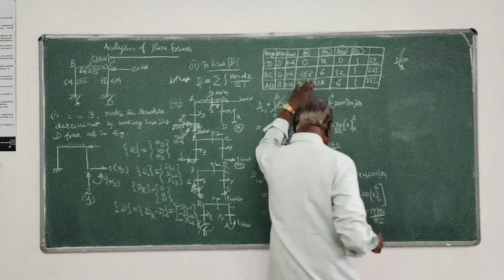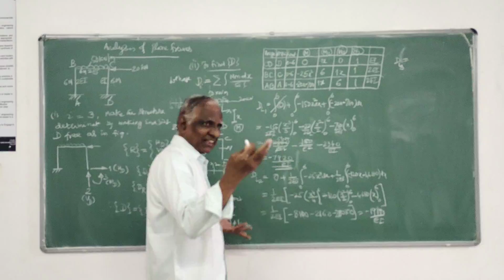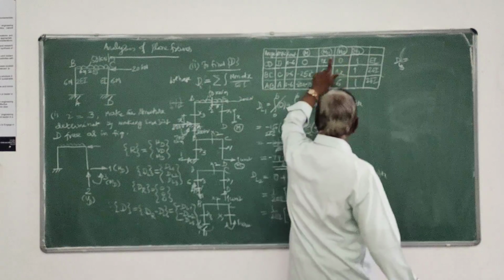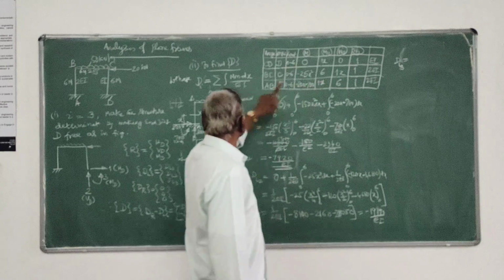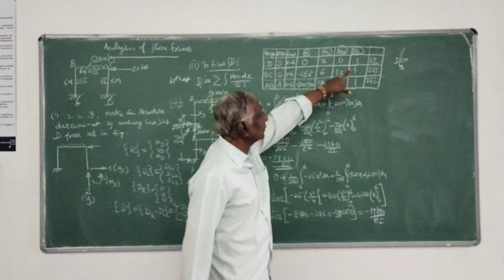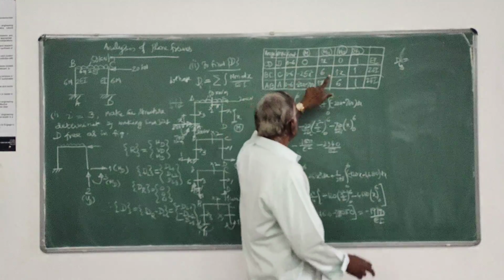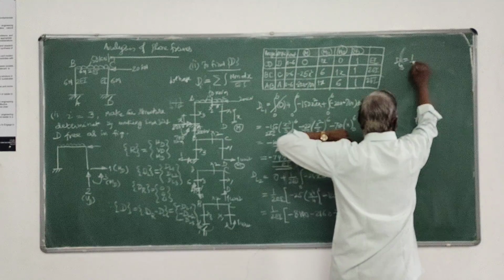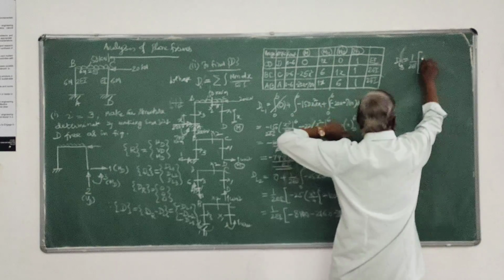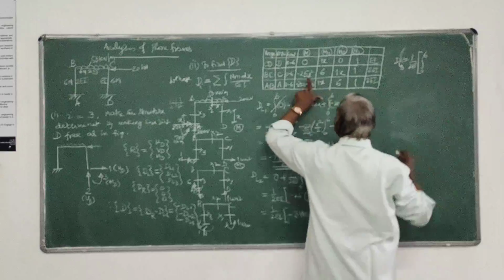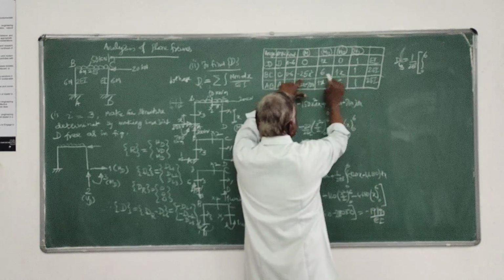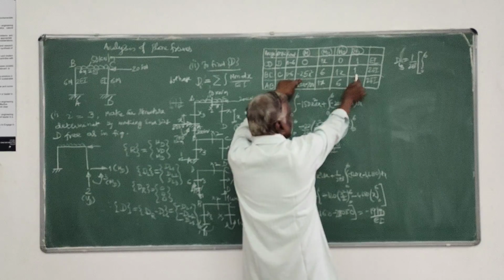This is the exercise that you have done in the previous semester. DL3 is, again from this table, M M3. M M3 I have to take. M M3 is 0 into 1, 0. Then it is only 1 over 2EI; I will take it for both. So integral 0 to 6, 1 over 2EI, 0 to 6, this into this. It is 25x squared into 1.